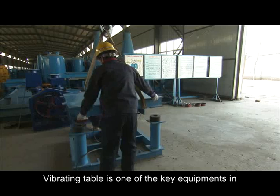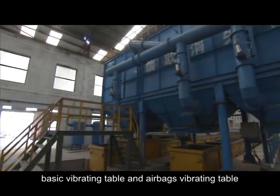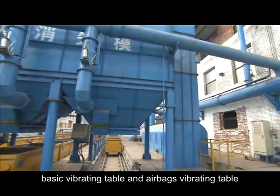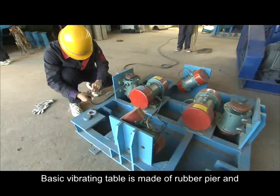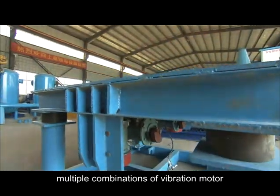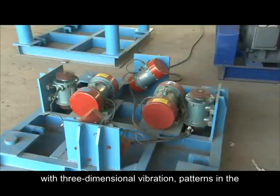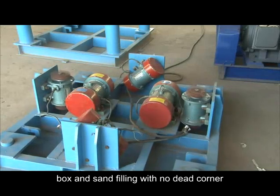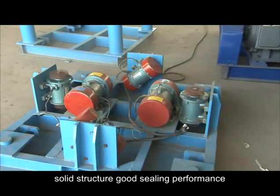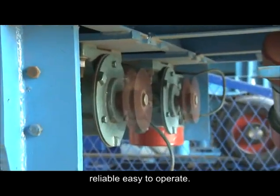The vibrating table is one of the key equipment in lost foam casting. It is generally divided into basic vibrating table and airbag vibrating table. The basic vibrating table is made of rubber piers and multiple combinations of vibration motors. With the three-dimensional vibration, patterns in the box and sand filling have no dead corner. It has a solid structure, good sealing performance, reliable and easy to operate.